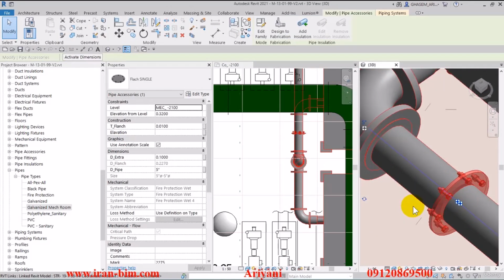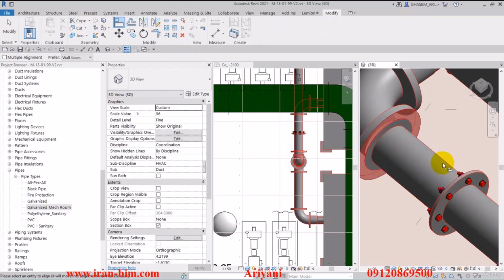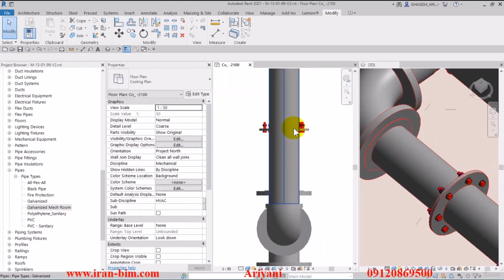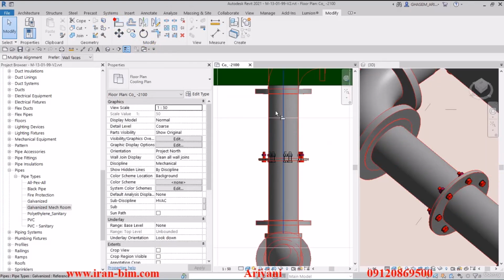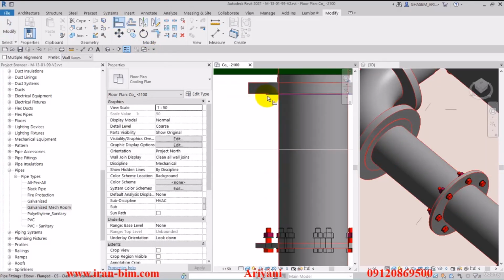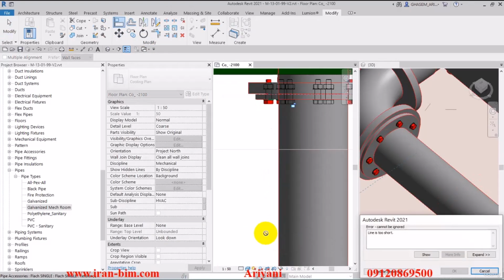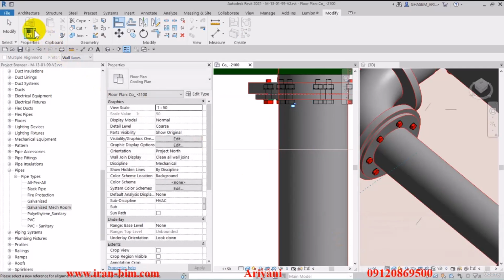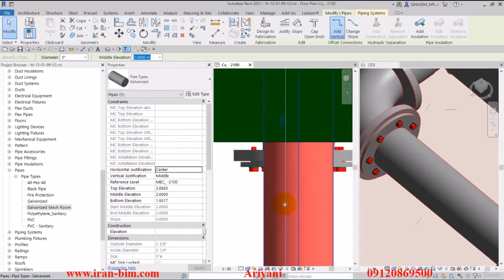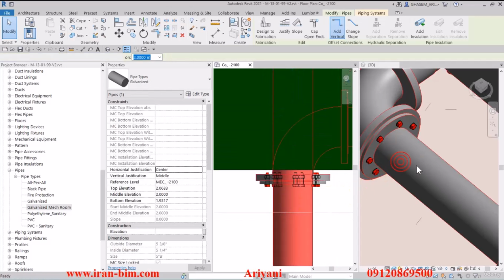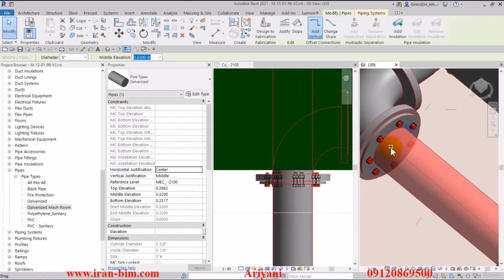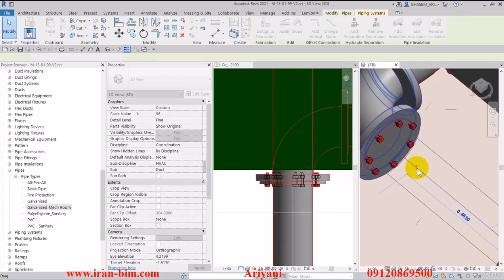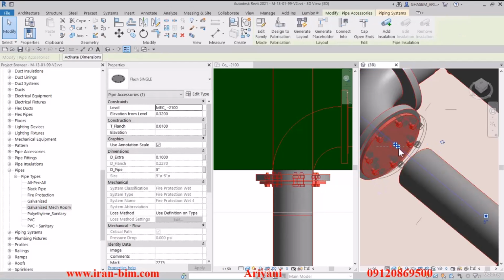All right, for now, we'll put it here from the top view. And this is how the flange is installed here. And we can use the align tool, or I can do it from the top view right here using the align tool to connect these up. All right, delete on this. This is because we'll be missing one of the pipe checks, and that's why we get the error. So we'll select the pipe over here and disconnect it from the system in order to demonstrate this.